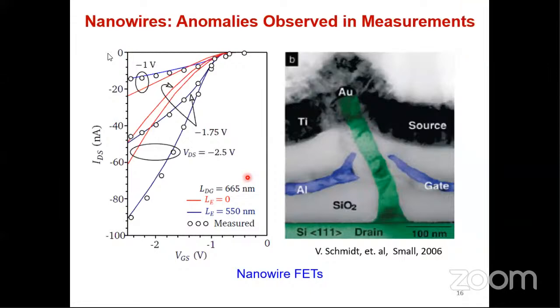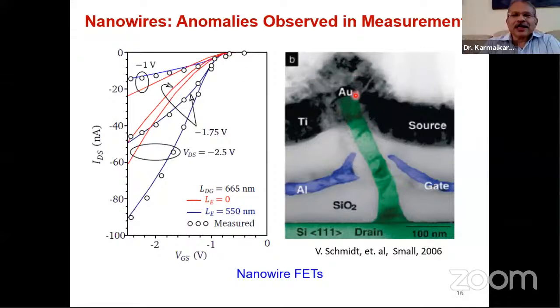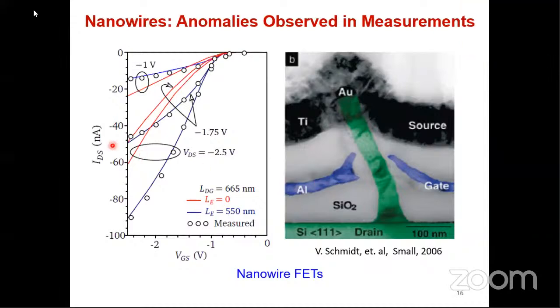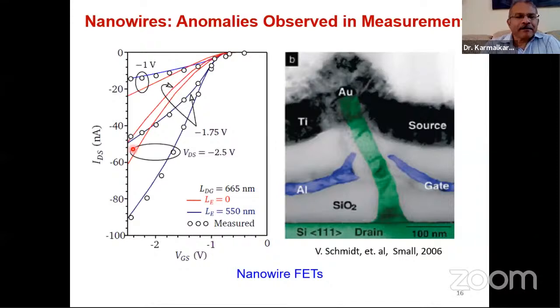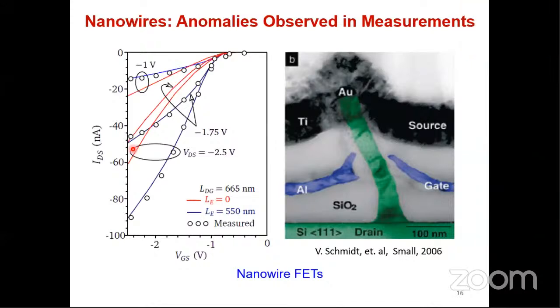Yes, drain current in a field effect transistor is a function of gate to source voltage as well as drain to source voltage. In other words, the current between drain and source is controlled by the gate, just like a water tap, where the flow is controlled through the wheel. Here we control the current by applying some voltage.